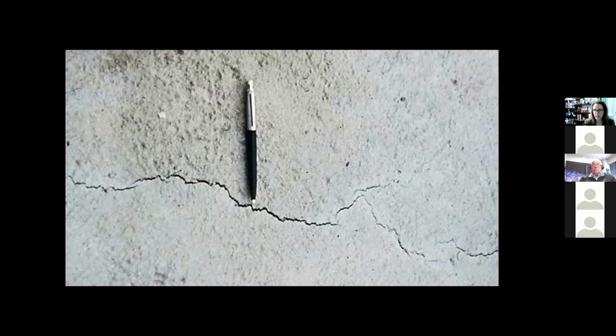If you see plastic shrinkage cracking and you're finishing the concrete, there are some guides out there that would encourage you to close that crack back up by finishing over it. There's some old manuals out there that might encourage you to strike both sides to close it together. The problem is the crack is not usually shallow. Plastic shrinkage cracking on its own is a durability problem if there is reinforcement in the concrete. And the reason being is we don't know how far down these cracks went and how wide they might get.